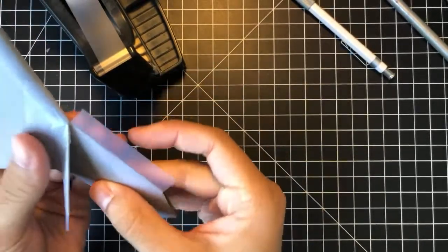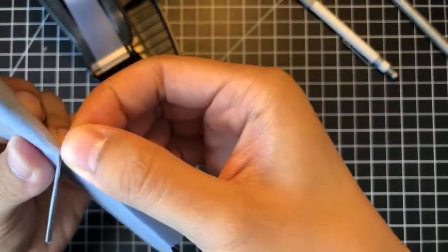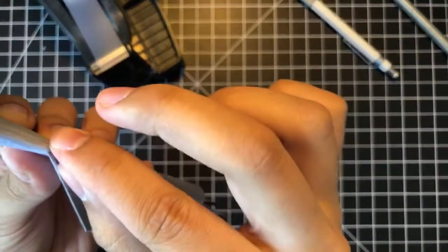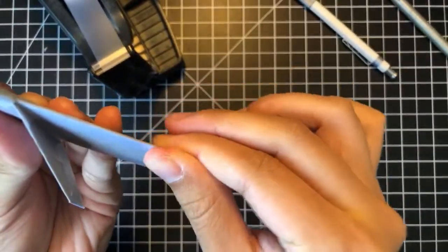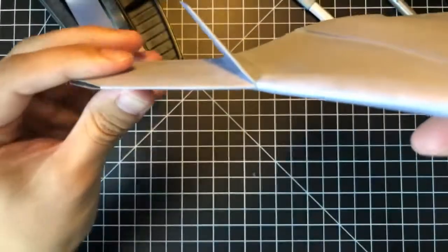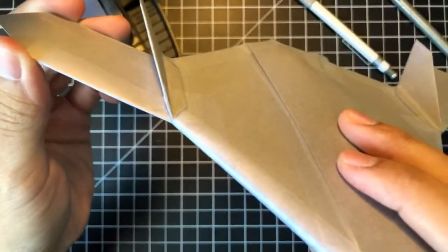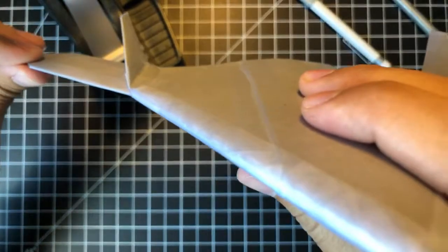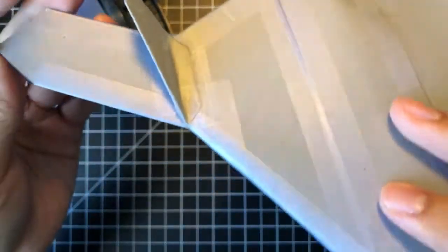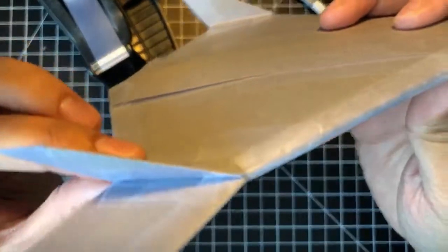I have to cut that later. But otherwise, this is standard procedure. You just tape over the leading edge to protect it, right? Because sometimes even when you flight test, you get debris hitting the wings. So this really protects it nicely from things like grass and leaves and dirt, right? So yeah, that looks really nice.